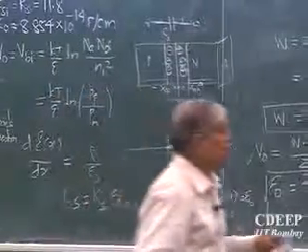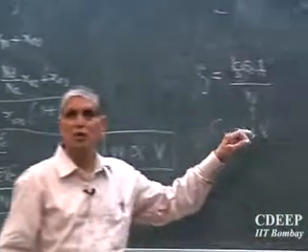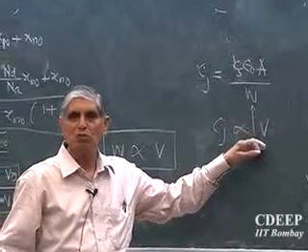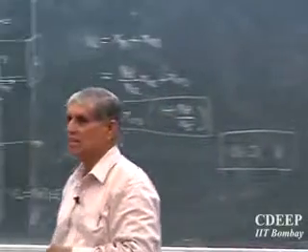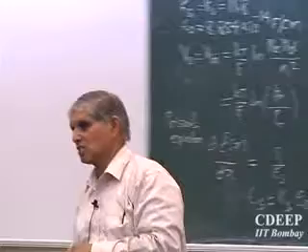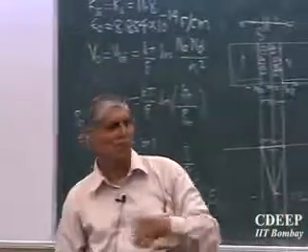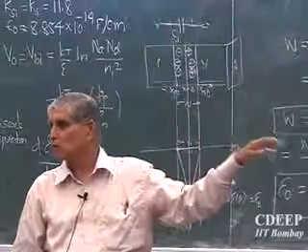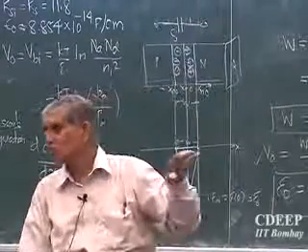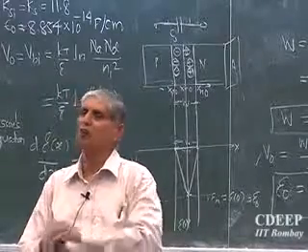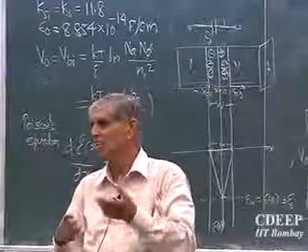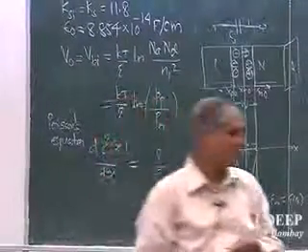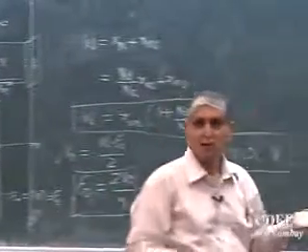So we were really looking for the relationship between Cj and V, because if that happens, by changing V I change C, and if I change C, I can change the frequency of operation. Is that clear? So this is the use of capacitance. There are many uses, but since there is no experiment on this in your lab, I thought I would tell you this is the major application which we use in almost every analog and digital circuit where you generate something. When you generate a signal, this is how you tune it. Is that point clear, why we are doing this?